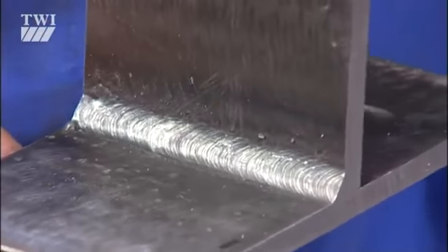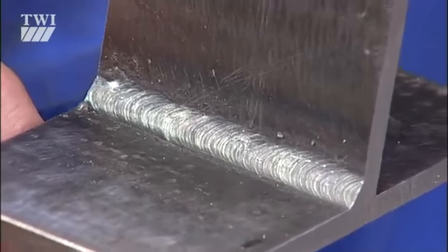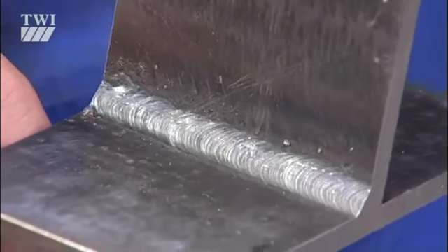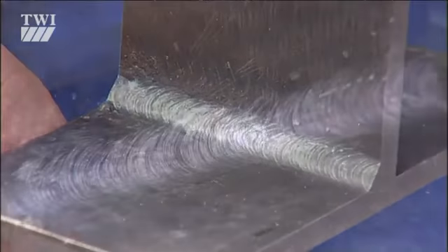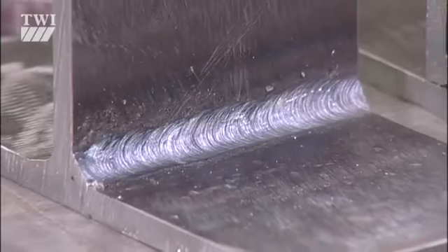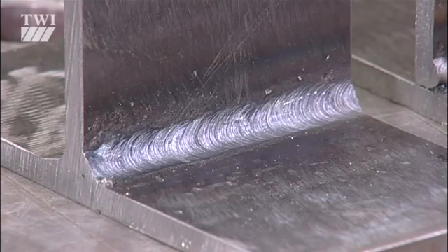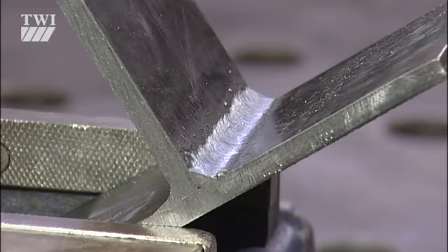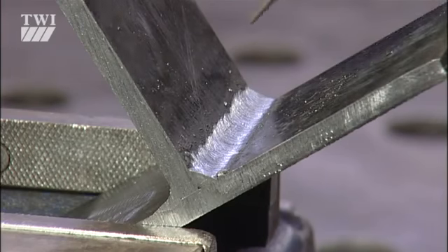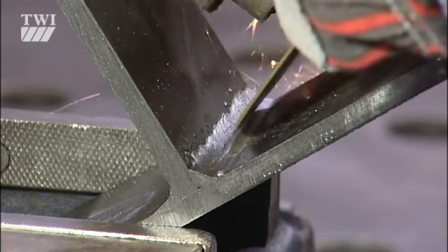Finally, the fillet fracture or weld break test, a simple and very crude test to examine a weld's soundness, often in a production environment on the shop floor. 2 plates are welded together on one side only in a T configuration. Of course, the base metal, weld metal, and welding parameters must adhere strictly to those prescribed in the welding procedure under scrutiny. The fillet weld is notched with a saw cut along its centre line.